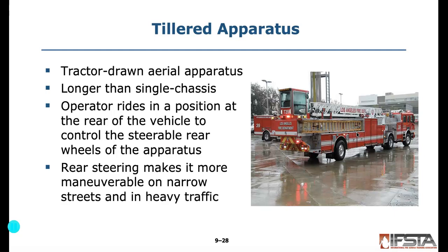Operator rides in a position at the rear of the vehicle called the tiller position. And they basically have a steering wheel in this little cab here, and you're following that apparatus and steering to go where you want the apparatus to go. So it's more maneuverable on narrow streets and then more maneuverable in heavy traffic.